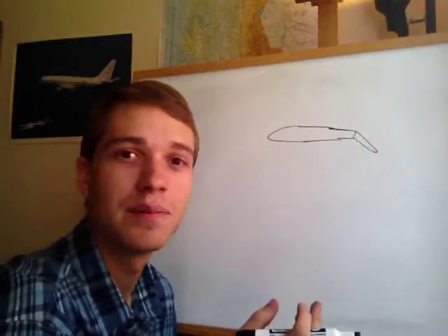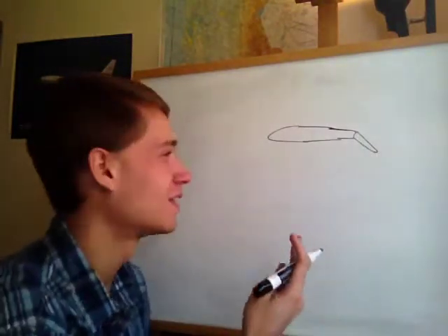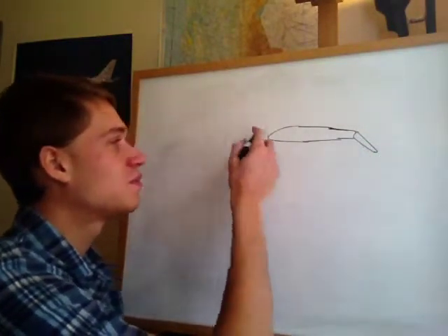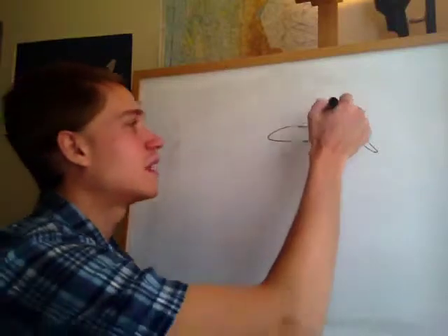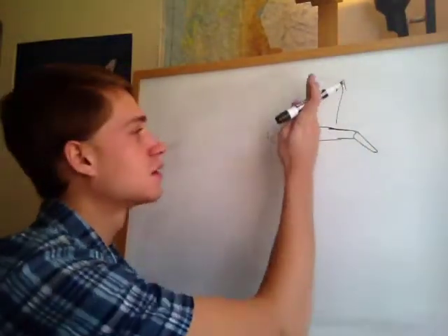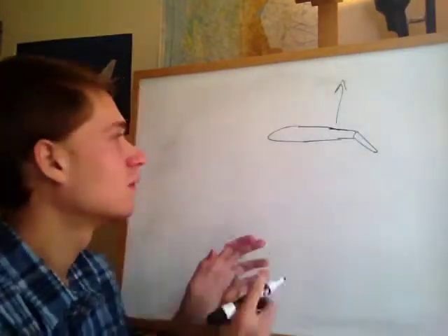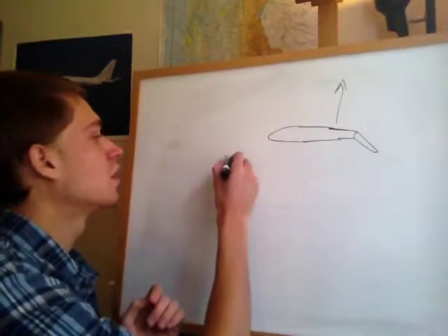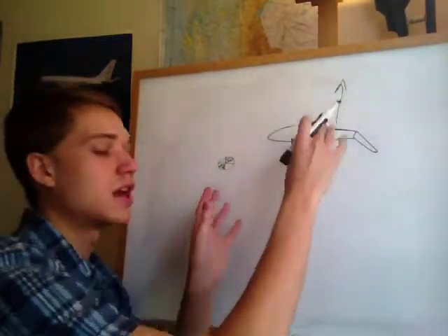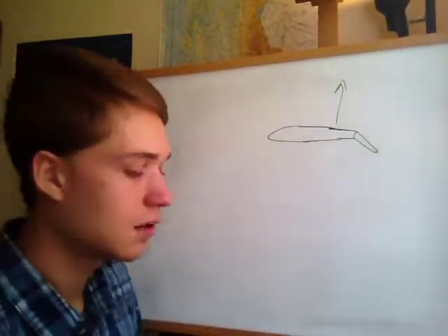Not like an airplane flap. It is on an airplane, but more like plain and simple, because there's 4 types of flaps that we're going to look at here. This is the plain flap, and simply speaking, a flap will increase the amount of lift that the wing is producing. At the same time, it's going to move the center of pressure back a little bit, and so if the center of gravity is over here and you move the center of pressure back, it's going to have a little bit of a nose down moment. That's an effect that you'll often have with the airplane.